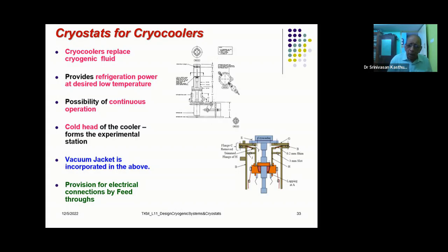A typical cryocooler using lead as the regenerator will go to 8 to 10 Kelvin for the second stage, and almost 35 to 40 Kelvin in the first stage. And if you are using a special regenerator material like erbium-3 nickel, holmium copper, etc., as we have discussed earlier, these can go to temperatures of almost 2.8 Kelvin in the second stage, and about 30 to 35 Kelvin in the first stage.